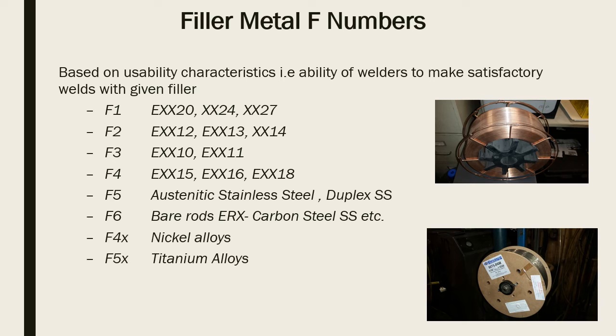You do a TIG test, you don't get the gas metal arc certs, even though you're using the same F6. And then you have things like nickel alloys, titanium alloys. There's copper alloys. There's a whole host of F numbers. So the welder qualifies with that F number. You've got to stay in your swim lane and weld only with that F number, unless there's some provision in the codes that give you other ones. Like I said, if you qualify with F4, you get F3, F2, F1. You've got to read the codes, though. The bottom line is you've got to read the codes and be conversant in the codes.